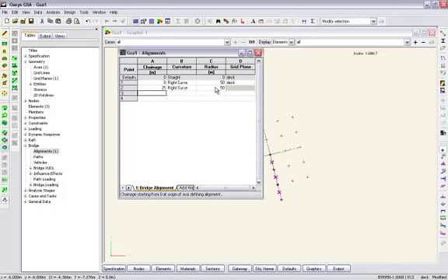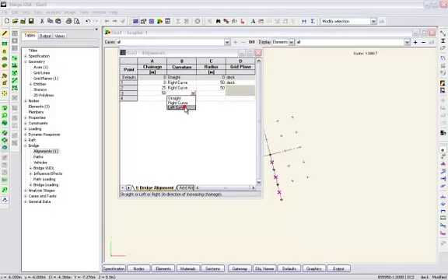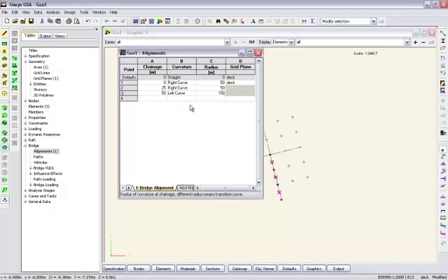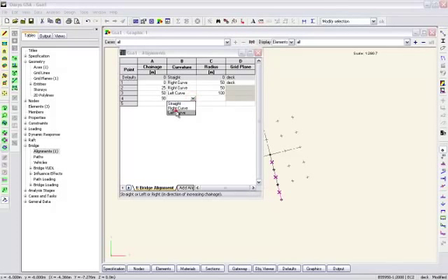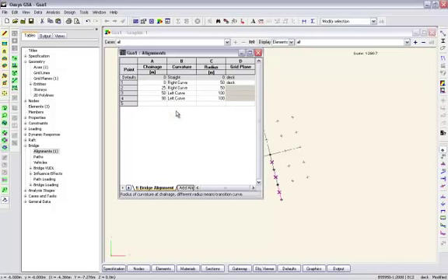So this will create a circular curve over the first 25 meters. Then at 50 meters I'm going to transition into a left hand curve which has a radius of 100 meters. And then at the far end of the deck, I'm making the bridge 90 meters long. Again, a left curve 100.